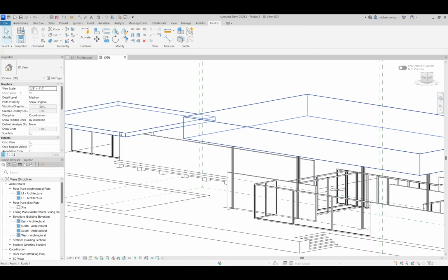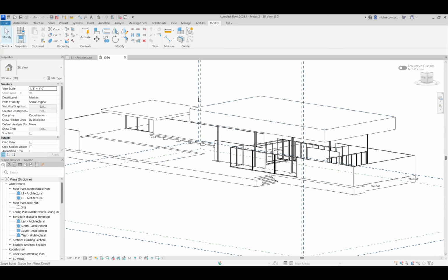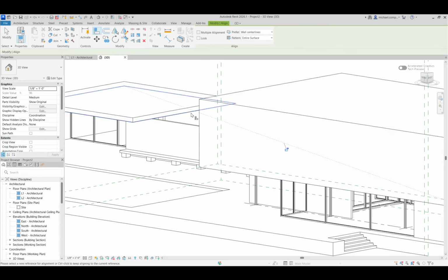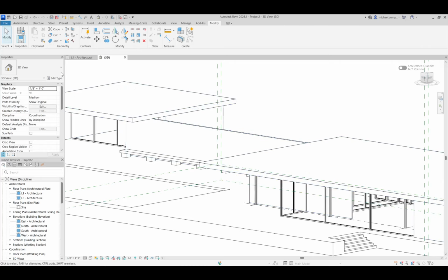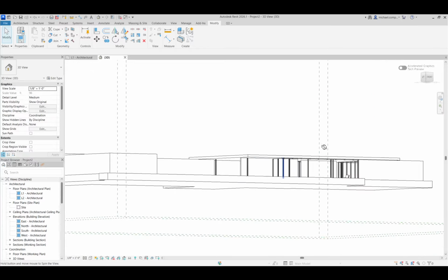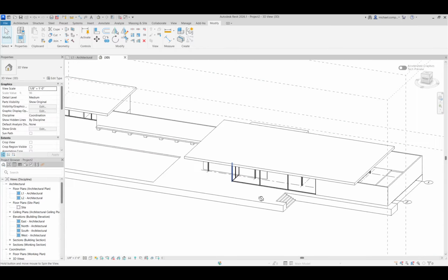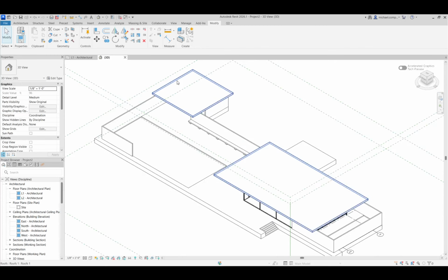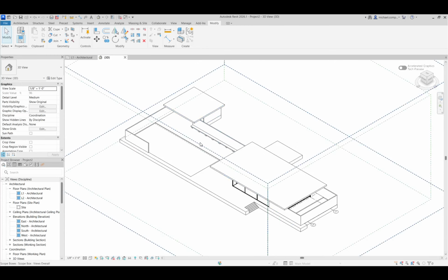And then I only did that for educational purposes. You wouldn't do it that way, but I can put the roof back by undo, or I can just do the align tool, which I just did, and align the tops of the existing roof with the other existing roof. Notice the columns went with it, and no extra Boolean modeling, cutting, voiding operation was necessary. I hope that was informative. I know it seemed chaotic when I was doing the family creations because it wasn't quite doing the things I wanted it to do, but hopefully you were able to stick with me.